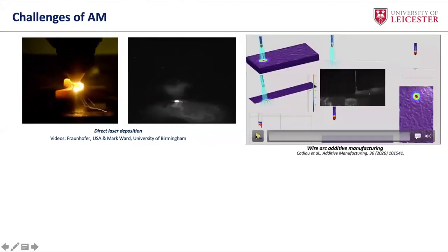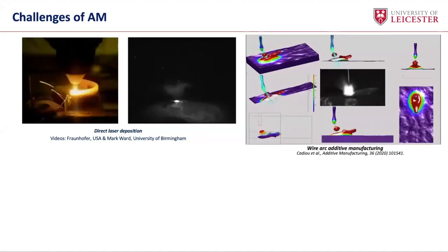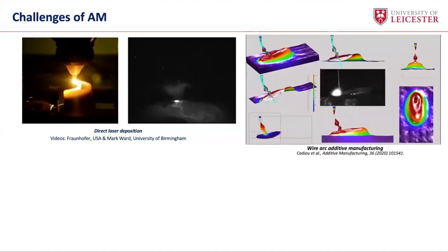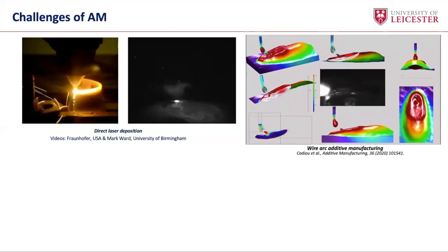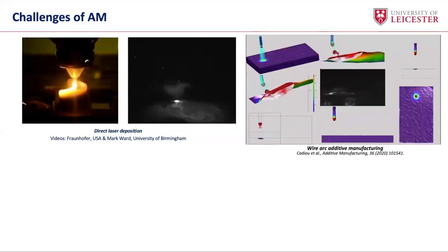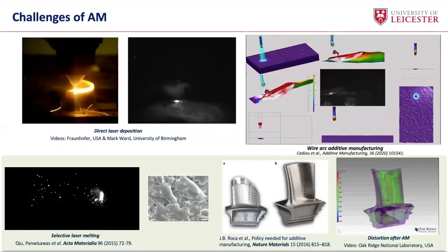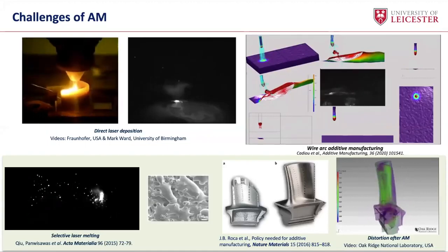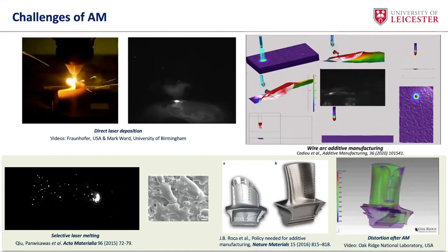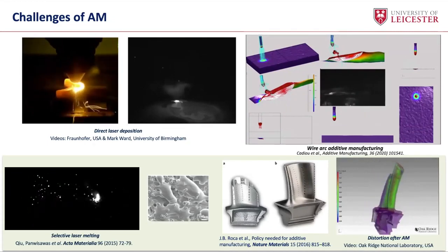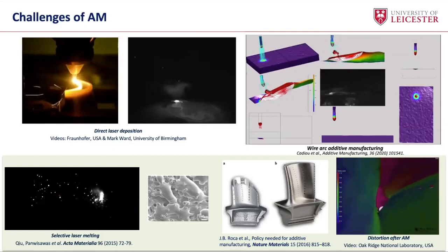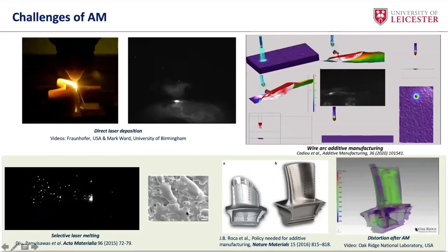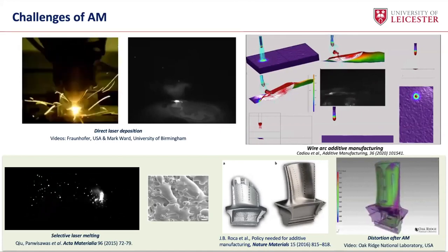Another technique, and also simulation result, that people are trying to do is in data published recently in 2020 in additive manufacturing. You will see that the detailed information at this micro length scale, about 100 micron here, can give you insight into the technology. How can you improve it? And the talk I'm giving today will focus on the 3D printing technique called selective laser melting, or powder bed fusion additive manufacturing. If you understand the processing science at the very low length scale, you will understand what the emerging microstructure is, and hence the property and performance.